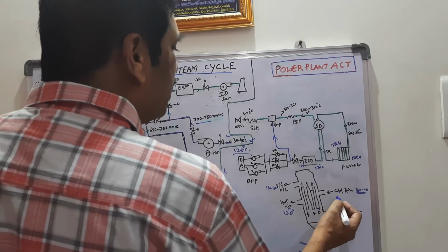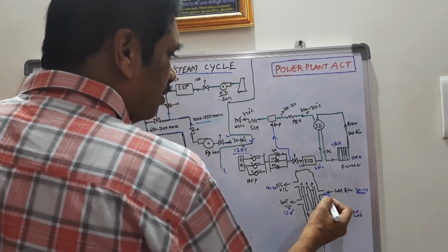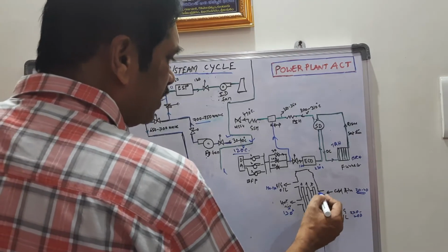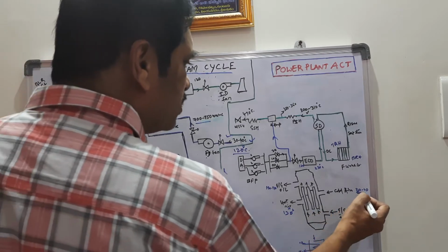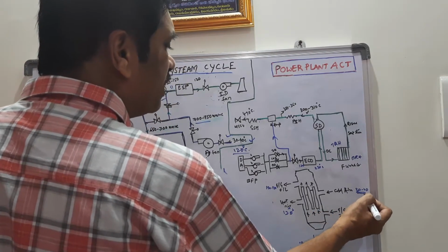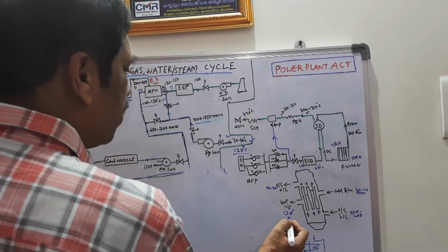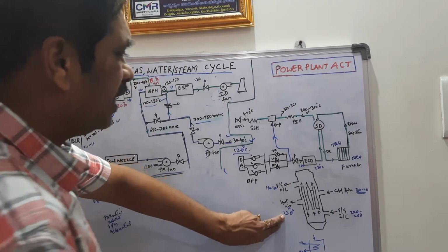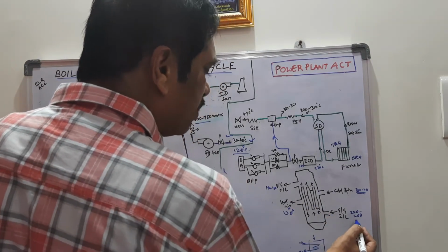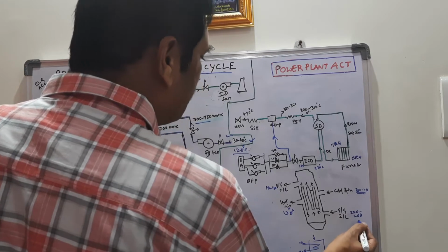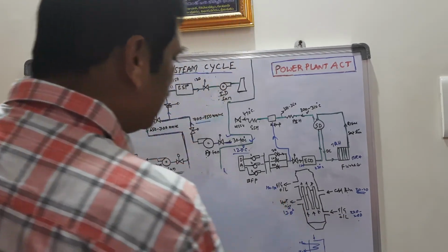And the cold air or ambient air enters at the top of the air preheater, outside the tubes, and it exits outside. So it enters at a temperature of 30 to 40 degree, and it comes out with a temperature of 120 to 130 degree. The flue gas entering is around 220 to 230 degree temperature, and comes down to 130 to 140 degree temperature.